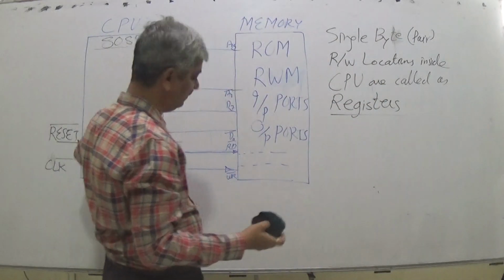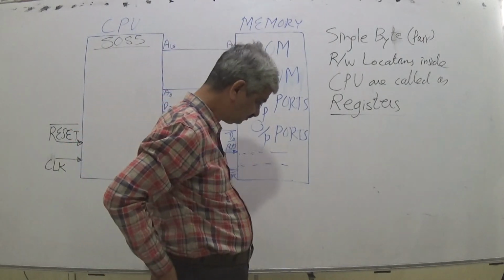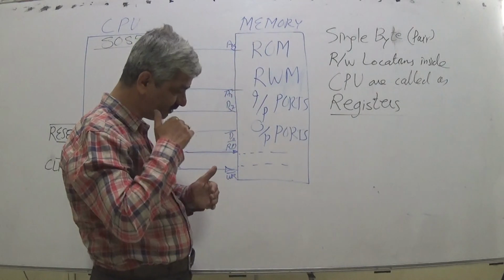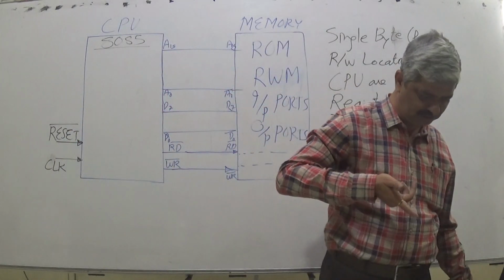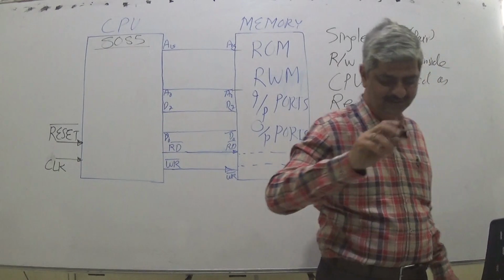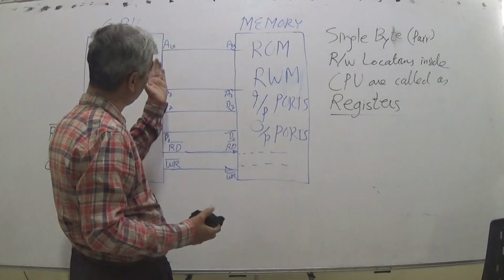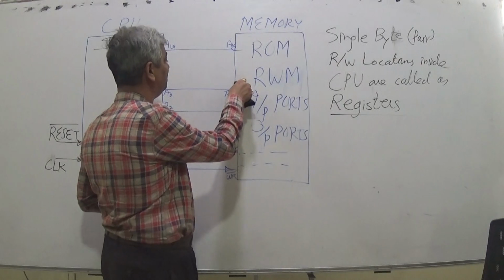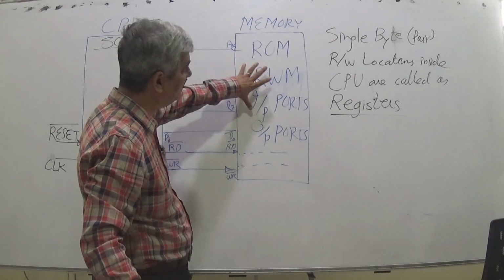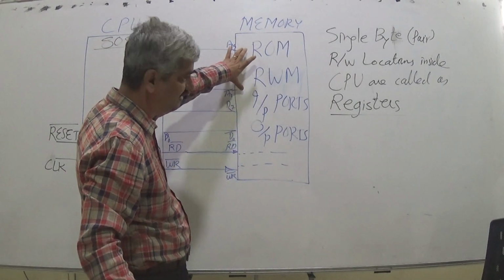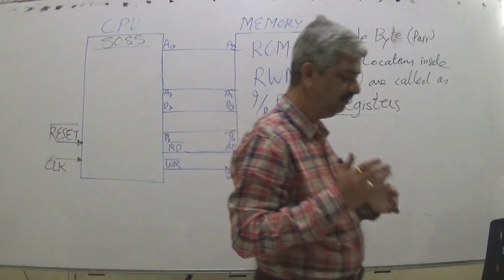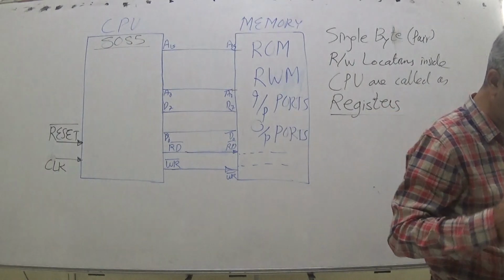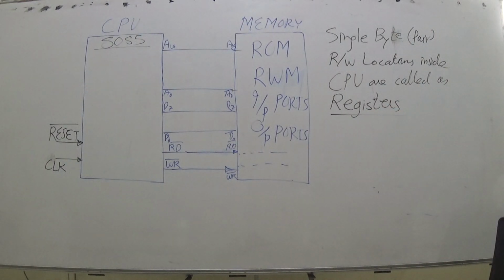So there are now... microprocessor is to be studied from application rather than theory. So what can be connected to a microprocessor? A memory block, which contains a 2:16 decoder, various... using address lines, data lines, read bar and write bar coming out from the microprocessor, where data are bidirectional.